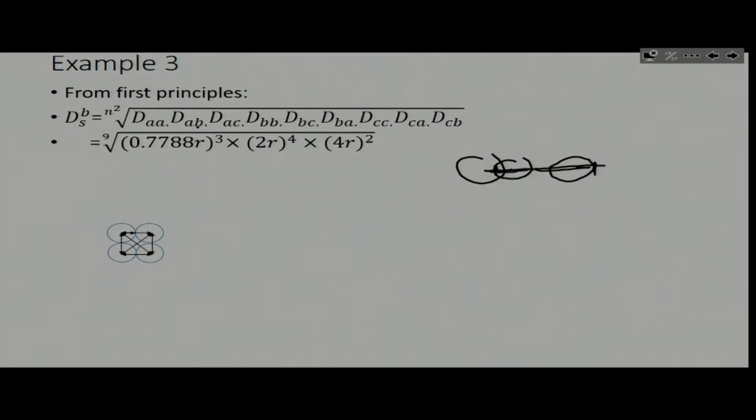And it's back and forth. Therefore, if we calculate everything there, we get 1.7037 R. Now what does that mean? That if we replace those 3 conductors by 1 conductor, it would have the radius of 1.703 of one of those radiuses.